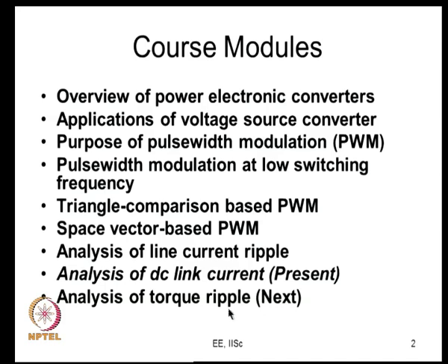That is, when you apply these kind of outputs of an inverter to an induction motor drive, the fundamental component of the output voltage produces fundamental current and fundamental flux, and that produces a steady torque, whereas all the harmonic voltages end in generation of certain ripple. So, this is what we will do in the next module, which would be in the next couple of lectures.